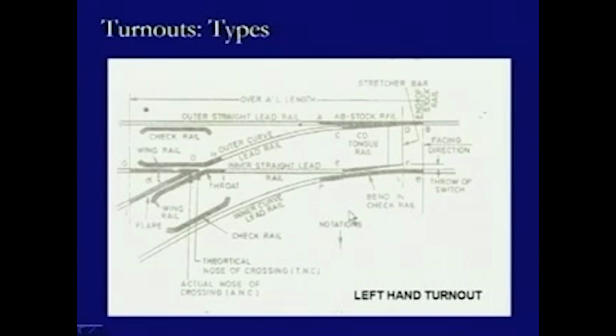Now, this is one diagram which shows the overall composition of the points and the crossings which constitute any turnout. In this case all the components can be seen very clearly. What we see is that this is one rail which is provided. There is one track which is being laid like this. These are the two rails of the track laid like this, and then there is a requirement of changing the direction from this track in this direction. So, there is another track which is being laid, and here in this portion there is an overlapping of the two tracks.